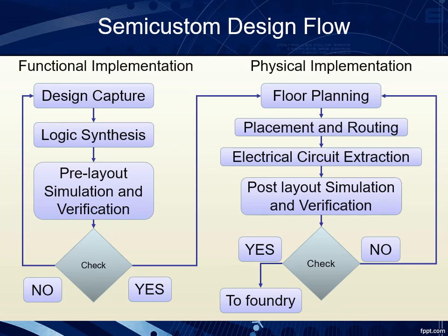The second stage is the placement and routing, in which we decide the exact position of each gate, governed by the constraints that are given by the previous stage. This stage, as we mentioned earlier, is done quasi-automatically in the sense that there are some software tools that can do it, but typically we still need to perform adjustments. At the end of the placement and routing, we already have a physical layout of the circuit on the silicon.